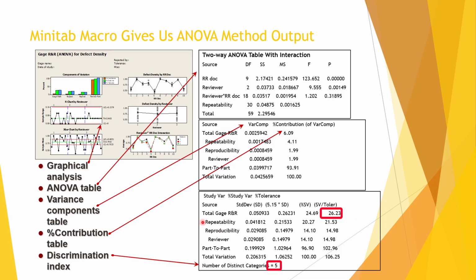So this is what you do. You go to total gauge R&R and you look at the final percentage. And remember what we learned, anything that's greater than 30%, it's unacceptable. So you know what this tells me? You produce your output that looks like this, and you look at this final number and you go back to your slide, just for accuracy and reassurance that you interpret it correctly, and you say it's either acceptable, somewhat acceptable, or proceed with caution, like the middle number.